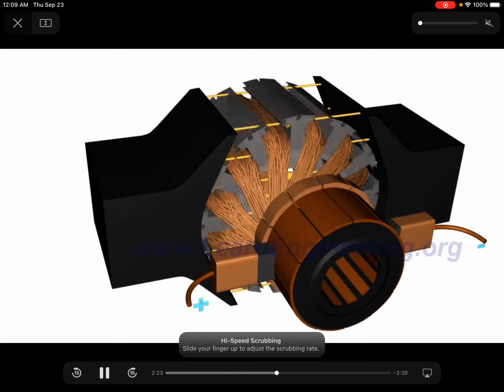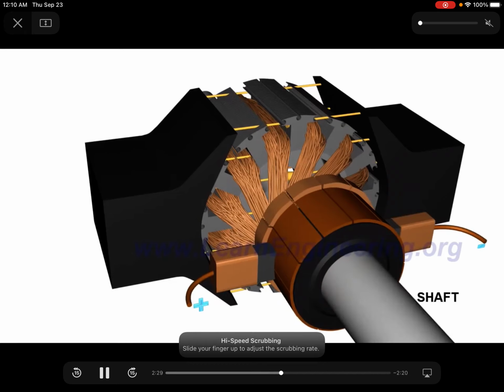Placing them, seeing this, now that is the iron core of the rotor. We are not placing these coils in the air, because we give the magnetic flux lines a better path to pass through, and these lines like to pass through magnetic materials. So we place this in an iron or a steel core like this. So this iron piece is what we call the rotor core, okay? And these coils are just placed inside this core like this.